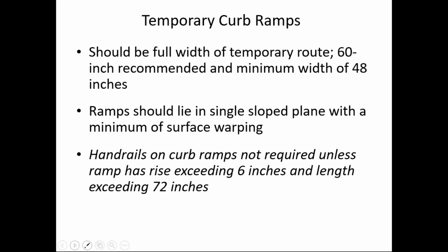And typically we don't talk about handrails on curb ramps. I'm not sure I've ever seen a handrail on a curb ramp, say at a corner, but with temporary ramps, notice, and I've italicized it to highlight it, for temporary ramps, if the ramp has a rise exceeding 6 inches and the length exceeding 72 inches, we do need handrails on the temporary curb ramps. So just something to keep in mind.